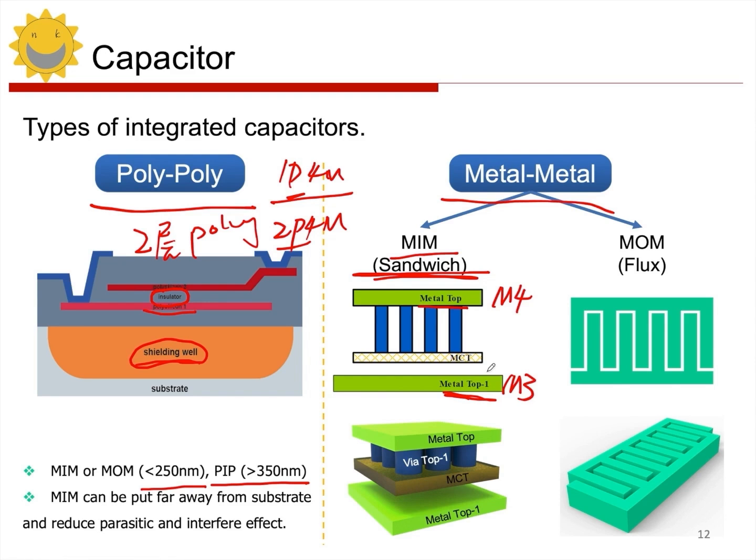And as we mentioned before, there must be an insulating dielectric between M3 and M4, right? There is definitely an insulating dielectric in between. So in this way, a capacitor structure has already been formed, right? I'm using M3 and M4 as the metal plates, and in between there's an insulating dielectric. There must be capacitance between these two layers, which creates a capacitor structure, right? This is a shell, and it indeed has capacitance, but the problem is that the capacitance density is relatively low.